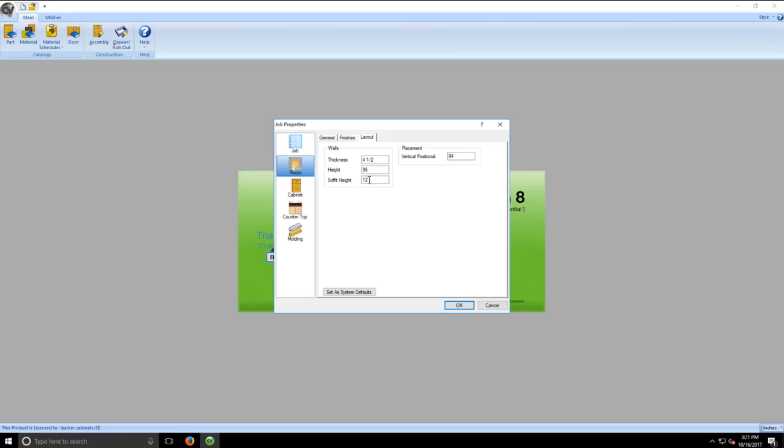Now, when I say right up to the top, I do not mean like, shove that cabinet so the doors are touching the ceiling. I mean, leave 4 inches below that and then run some 4-inch tall crown molding. A lot of people say, why do you want to run a 4-inch tall crown molding above your cabinets to the ceiling? Ceilings, especially in older houses, are out of level. They can have waves in them, bows, they settle after a while. And the idea with the 4-inch tall gap is you use a 4-inch crown between your cabinets and the ceiling.